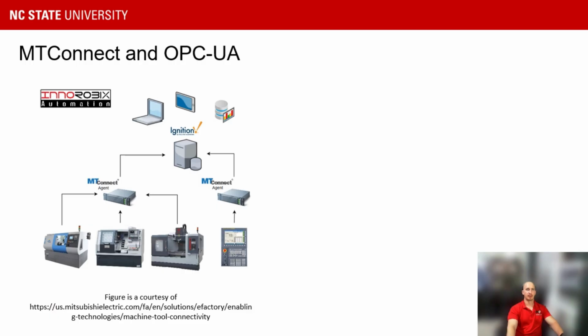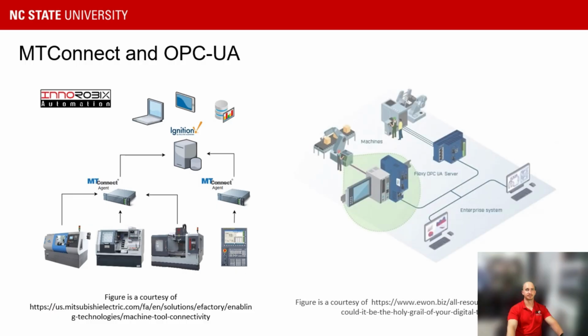The biggest drawback is that someone needs to create MTConnect agents and adapters, which most likely will need to be performed by the original equipment manufacturers. Unfortunately, not all equipment has a built-in MTConnect agent, and even those with it might not give all the information needed, like HAAS MTConnect.